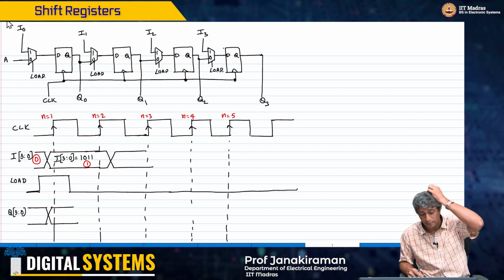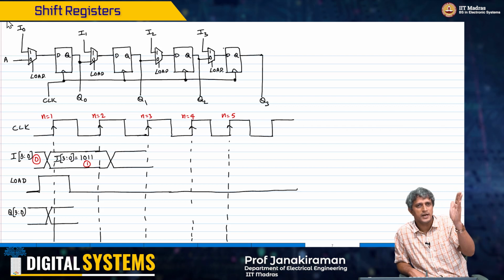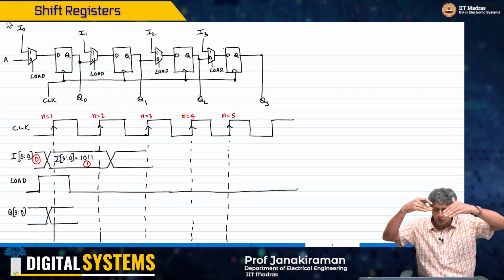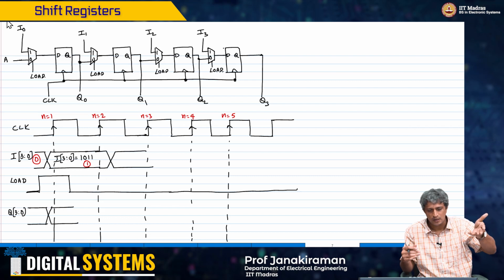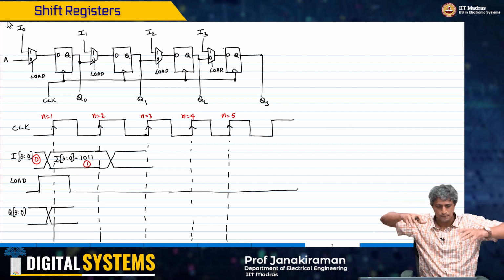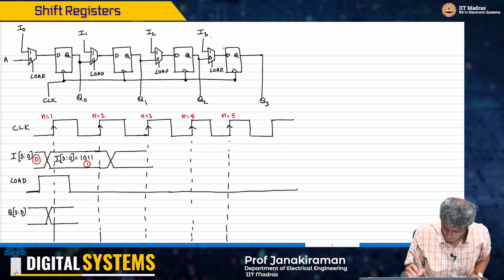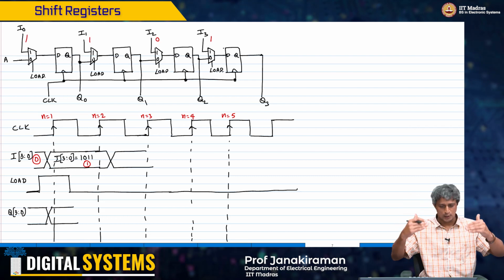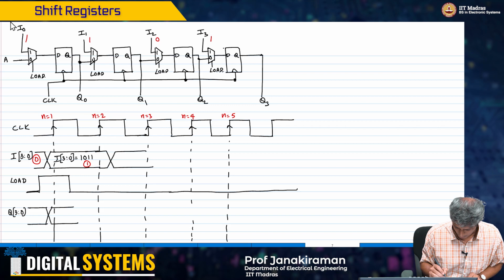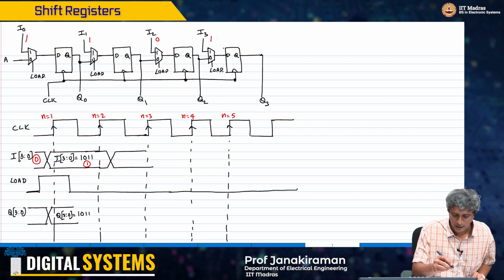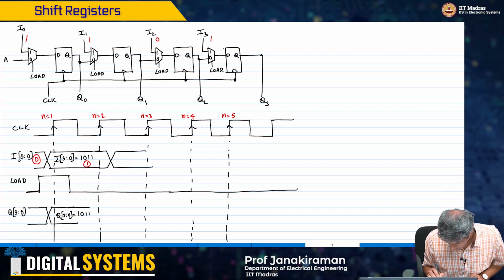And therefore, what will happen is, the moment the clock samples the data at sampling edge n equal to 1, I3 to 0 will simply appear. Load has gone high at the input to the multiplexer, and therefore the data which has already settled to 1011 is also available. So that data will just get loaded and appear here. So my Q of 3:0 will be 1011. It will simply appear at the Q at the first clock edge.